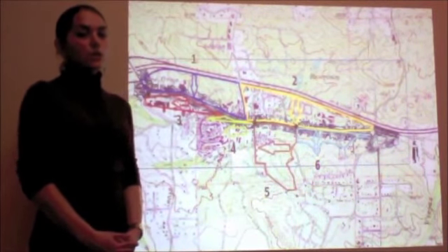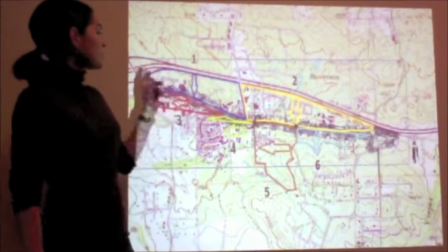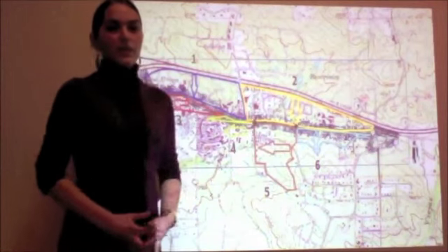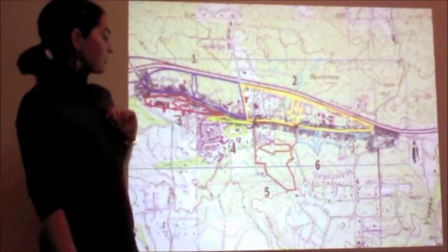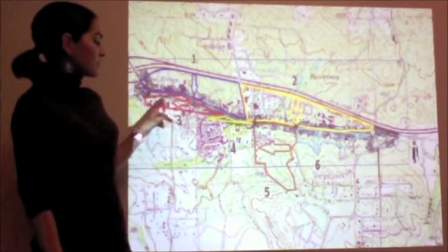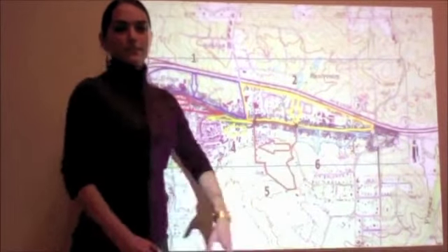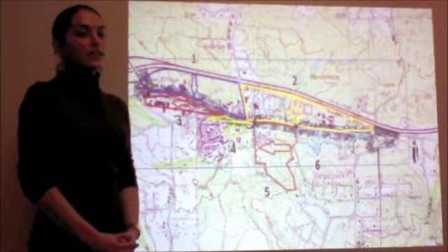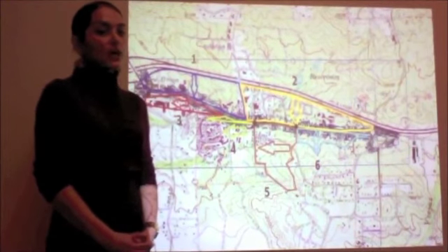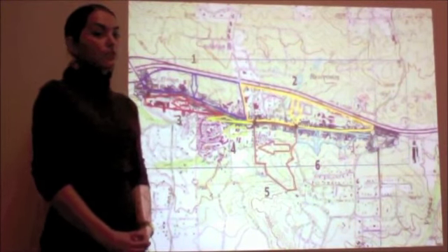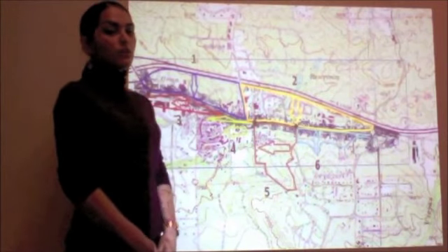The 2 largest watersheds were identified north of Alpine Boulevard. They were described as System 1 and System 2. Heading south of Alpine Boulevard, 4 other systems were described: System 3, 4, 5, and 6. Once the watersheds were identified by separate systems, the area was calculated for each, and then the rational method was used to calculate for the flow. The next step after calculating the flow was to begin designing for the culverts.